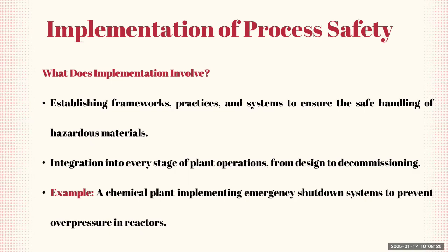So when I see that my pressure increases more than 10 bar, I will add a system, for example, called a rupture disc or a device that would release the pressure somewhere else. So either to a safety system, usually not to the environment, but as a worst case scenario, if our vessel is not containing a very toxic material, we could also release it to the environment so that the overpressure can be avoided.